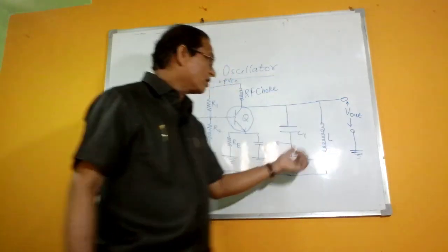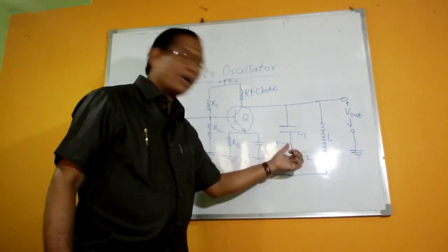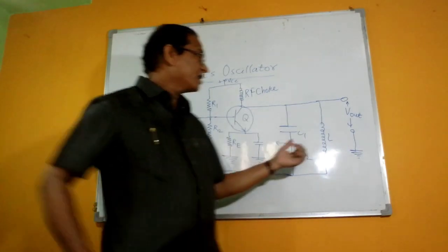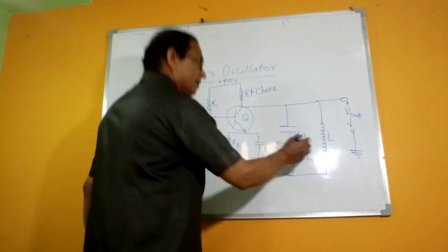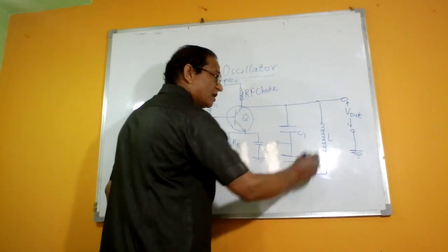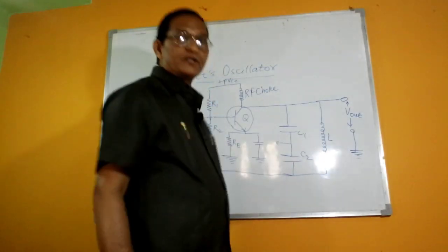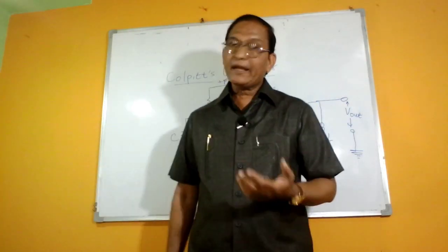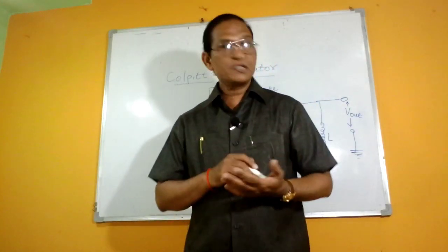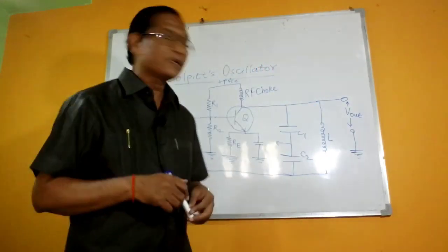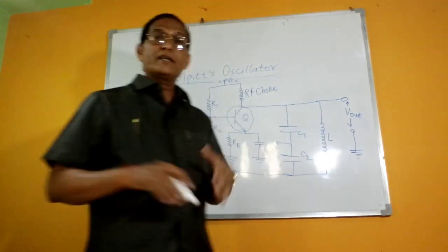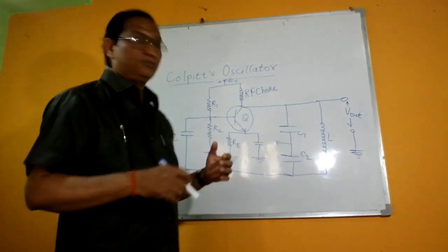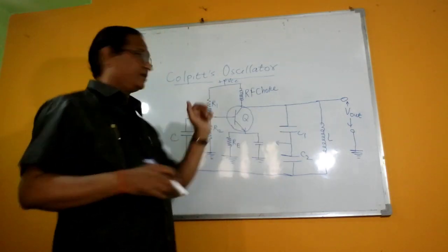Then further these capacitors are again charged, getting the energy from the inductance coil. That is, the magnetostatic energy is then converted into the electrostatic energy. So this is repeated again and again, the electrostatic energy being converted to the magnetostatic energy, and the magnetostatic energy being converted to the electrostatic energy, so that the oscillations are set up in the tank circuit.